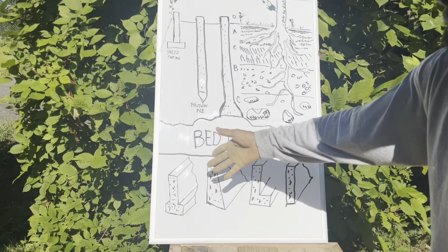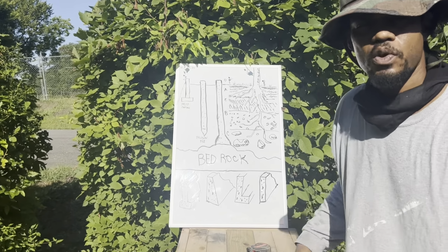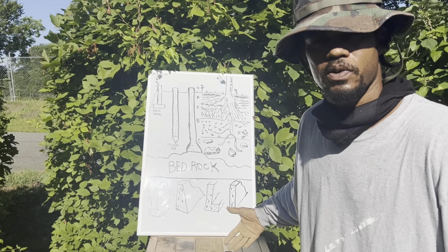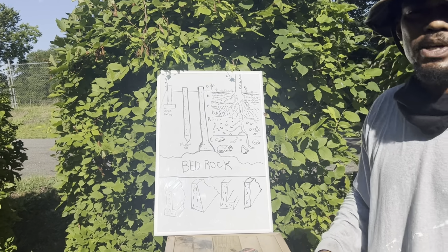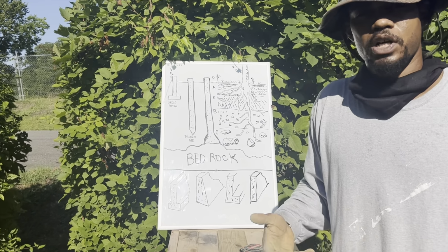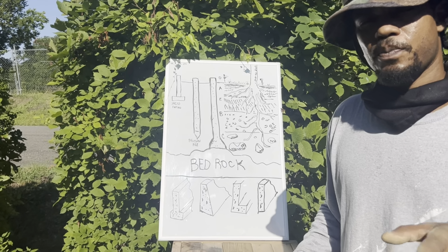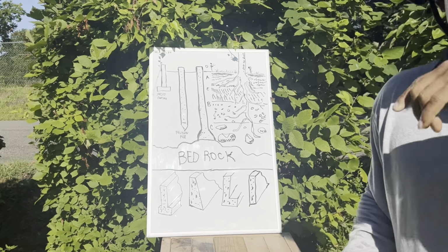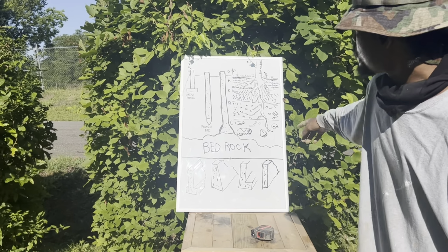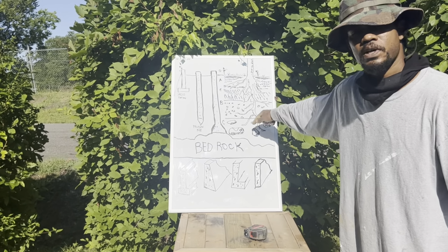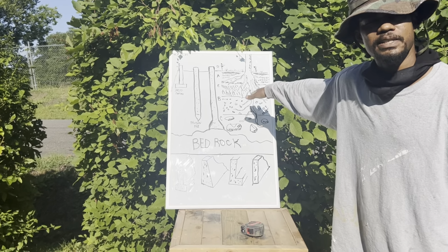Another thing I want to tell y'all about is when you go down in your soil, you also have groundwater. You got to be aware of that. You want to be a general contractor, you want to be a temple builder, you want to be a carpenter. A lot of this stuff is technical, I know, but you got to know all this. You will have groundwater in this soil, and you also have your frost line to identify.